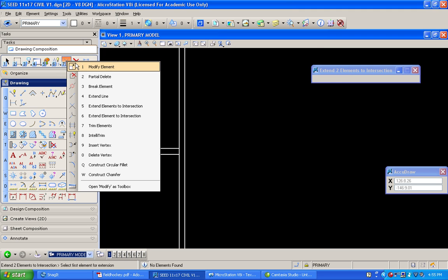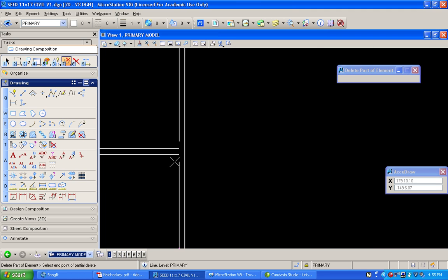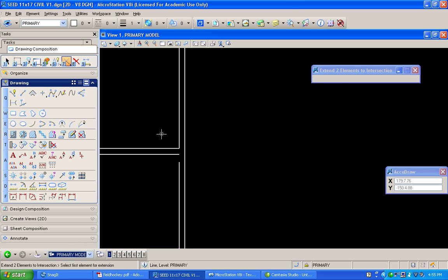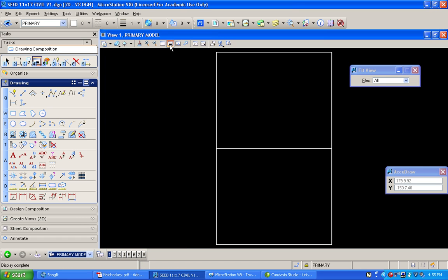Next, we're going to put in the 25-yard line. So we'll zoom into the upper area of the field. And what I can do is take this inner line that we drew initially and copy it up 25 yards, or actually 75 feet.